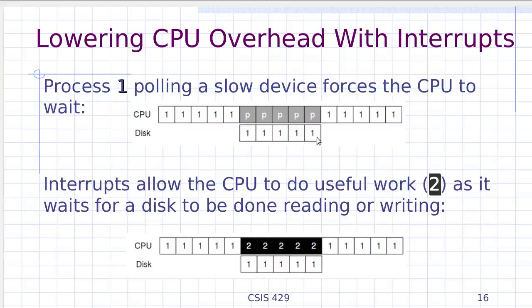And then once it's done, millions of cycles later, the CPU says, okay, it's done, I can do something else now. So this is a very inefficient use of the CPU. You can do this, it's not unreasonable. Sometimes you have very fast I/O, but if it's slow, it's not a good use of the CPU, and you would switch to doing something like interrupts.